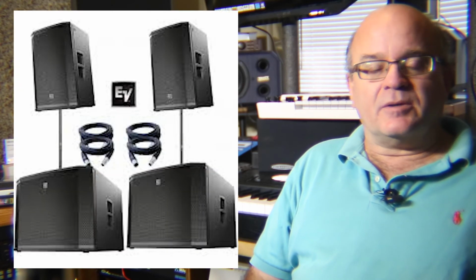It serves two purposes. Number one, you can direct more energy directly at more of the audience as opposed to shooting mostly over their heads in the straightforward position. To some people, it looks a bit strange, but it works very well. The other advantage is you can keep that energy from unnecessarily bouncing off the rear wall, which in some rooms can adversely affect intelligibility with all the slapback and echo bouncing around the room.